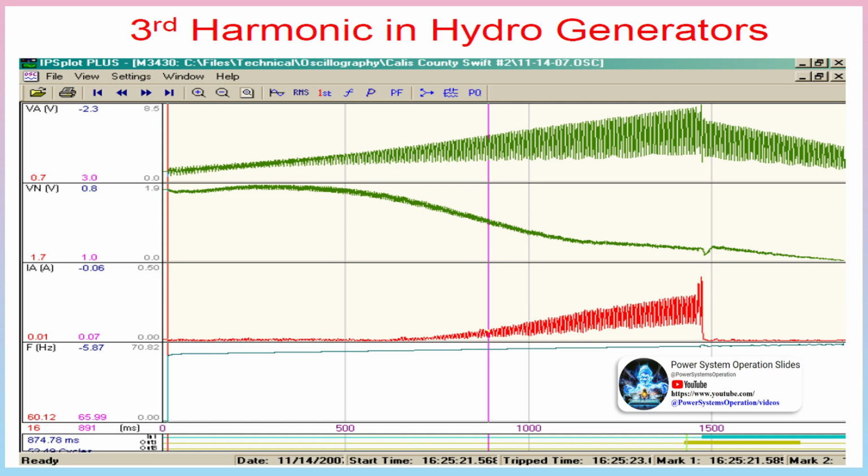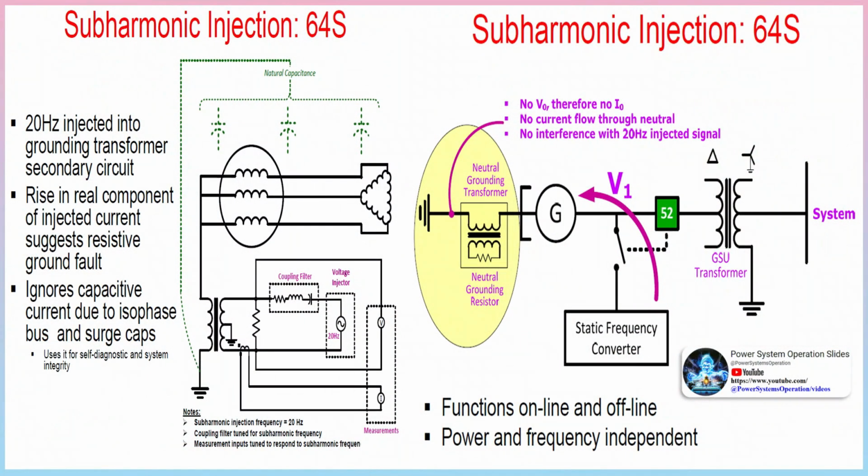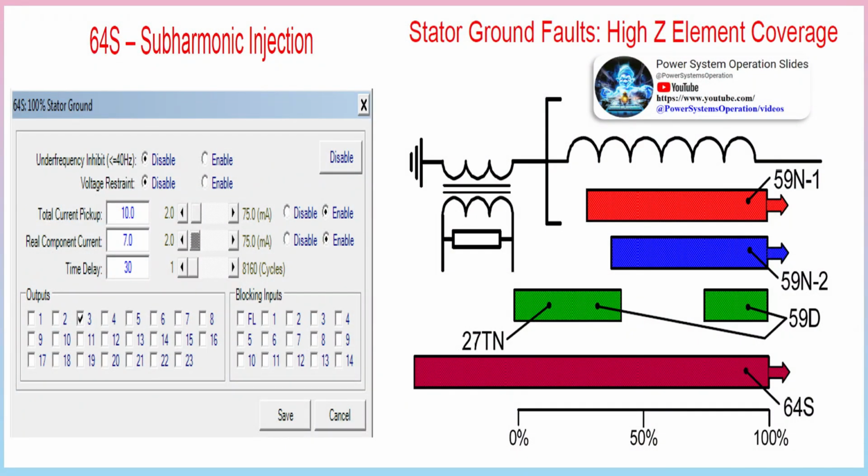Smaller generators, normally below 30 megawatts, are not equipped with embedded temperature coils but are usually fitted with thermal relays arranged to measure the current flowing in the stator winding. This arrangement only detects overheating caused by overloading and does not provide any protection against overheating due to failure of cooling systems or short-circuited stator laminations. Overcurrent relays, negative phase sequence relays, and devices for monitoring coolant flow are also used to provide a certain degree of thermal overload protection.